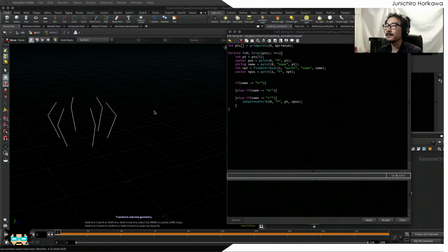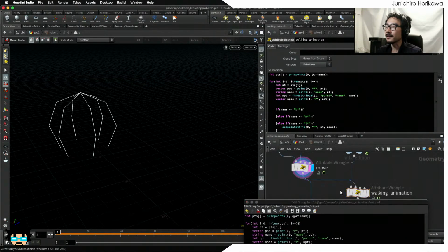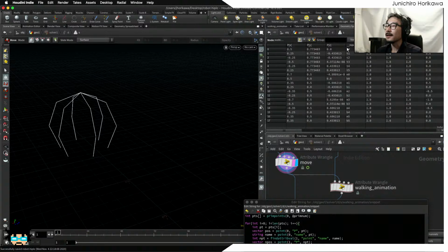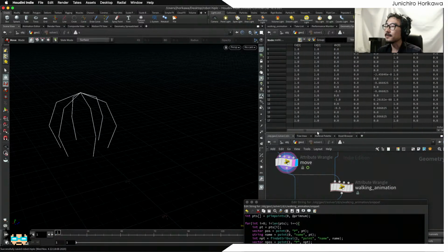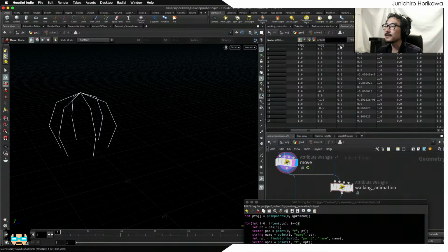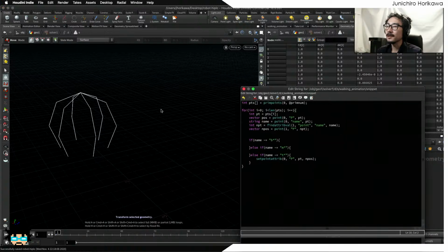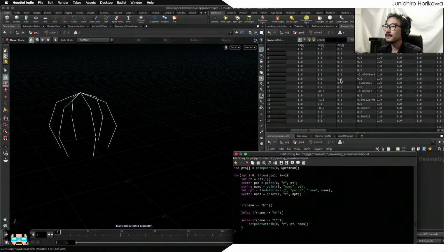That's when you want to use the value that you created previously, which is added as a direction attribute at the point only for the middle, which is this one. You can use this directional attribute to move the average point between this point and this point in that direction to define the new point position for this middle point. Okay, so I'm going to use that one.